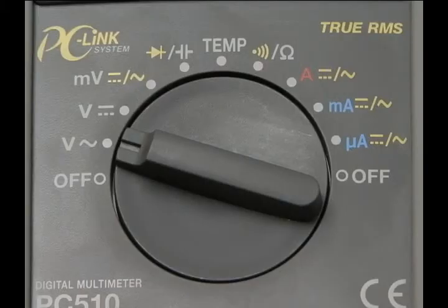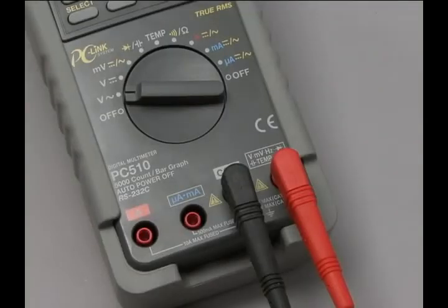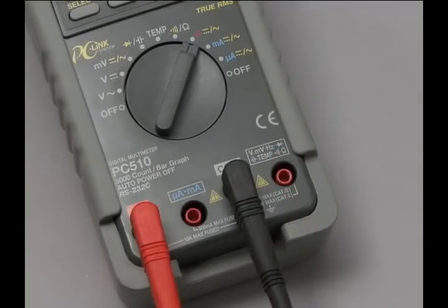Items to be measured are selected by the rotary switch, but because in many cases range setting is done automatically, there is no need to set the range. With the digital tester shown here, measurement of voltage and resistance is automatic, but the range setting for current is manual. The test lead contact point differs only when measuring current.